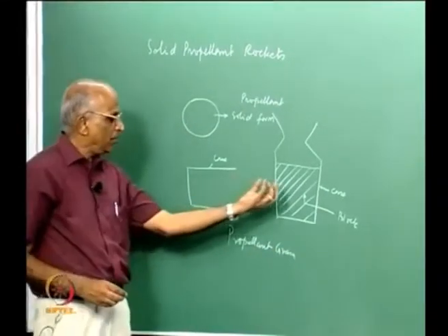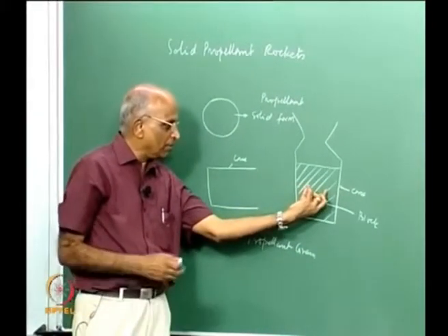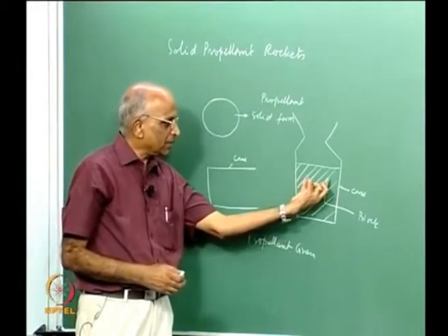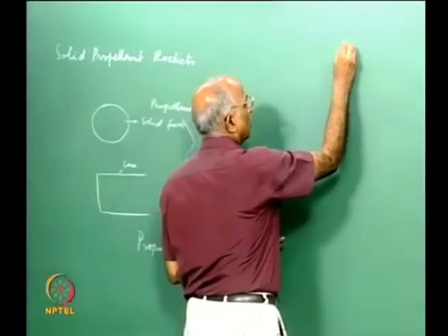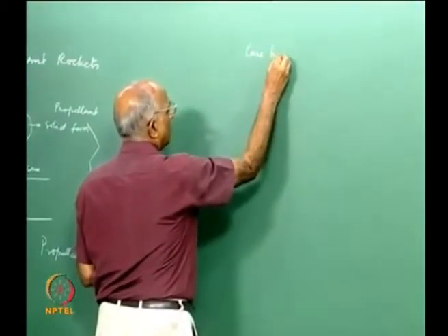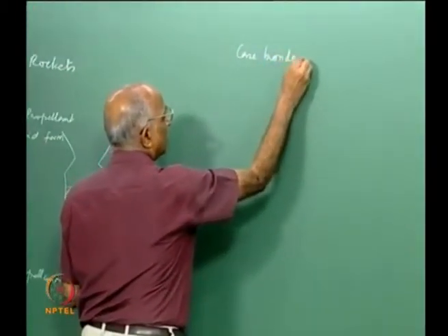And when I cure or I put the slurry or the mixture in it and make it as a solid inside a case, the rocket or solid rocket is known as case bonded. It is also possible to make the propellant in the form of a paste and extrude it out, just like we squish out the toothpaste from its container.